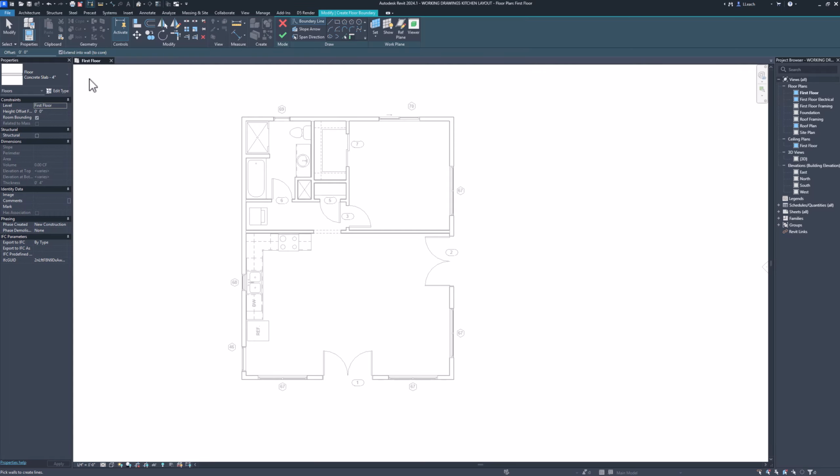All right, so I'm going to select my concrete 4-inch floor slab. I'm going to click on Pick Walls in the Draw panel here, and I'm going to select the outside face of each wall. So 1, 2, 3, 4. Now you notice that this one, because it's the first one I selected, has the span direction.